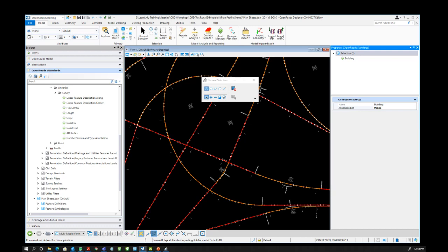If your mindset is still using the other software, then it's still okay. But I think the issue in that is that it will give you the headache later on, because I'm also a user of that software. If you notice when you're creating a file, you're loading the entire DWT file in the same DWG file. And then you're creating your terrain, survey, corridor, your other edits in the same DWG.